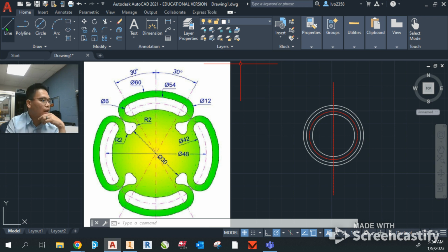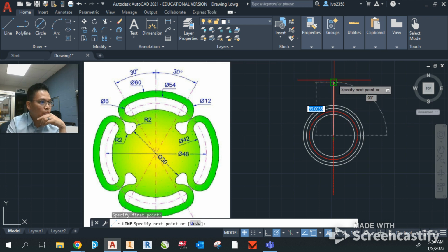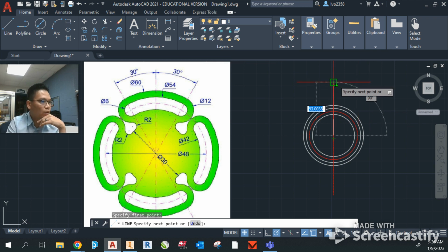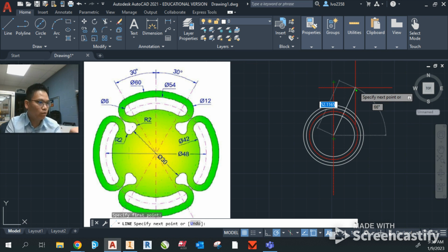Next, what I'm gonna do is I'm gonna rotate this to an angle, or I can create it. So let's start with that first. Let's create a construction line. So right here, you can see this whole angle is 90 degree. If I move my mouse to the right, you can see that number is getting smaller. So now I'm at 45. I'm at 62. I want the angle that is not being numbered right now to be 30.